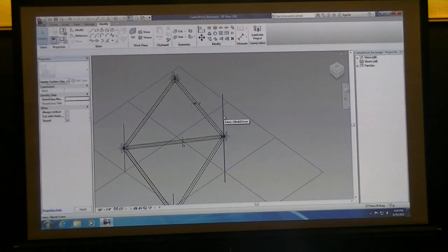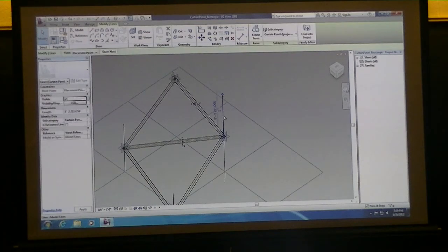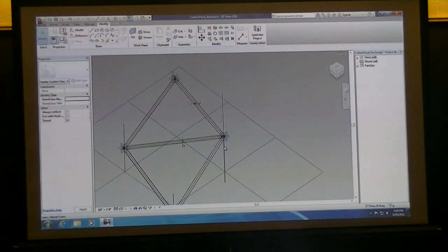And then if you tab over that line, you should see where you can select the individual half, delete those, so that you basically have that long line again. Then it'll work. Basically what you have to do is select the half arc and the line and say create form, and it'll create your